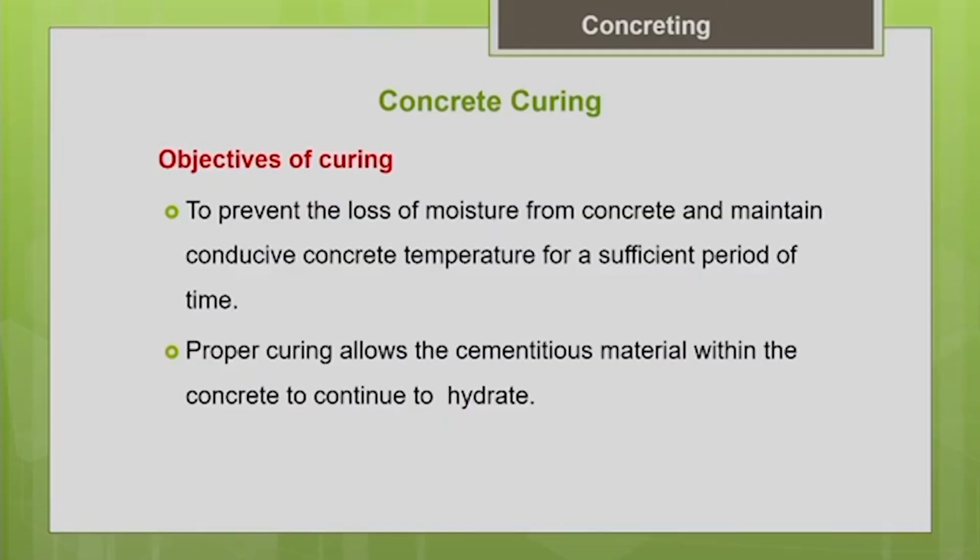But basically, whatever water you have added for preparing the concrete, that water itself is sufficient for the hydration process. In most cases, the water we have designed for concrete making is sufficient for hydration. But what happens is, when the concrete is exposed to the ambient condition, the water from within the concrete is lost to the outside environment. That loss of water affects the hydration process. Because of the loss of water from the concrete to the outside environment, the water is not available for the hydration process of the cement.